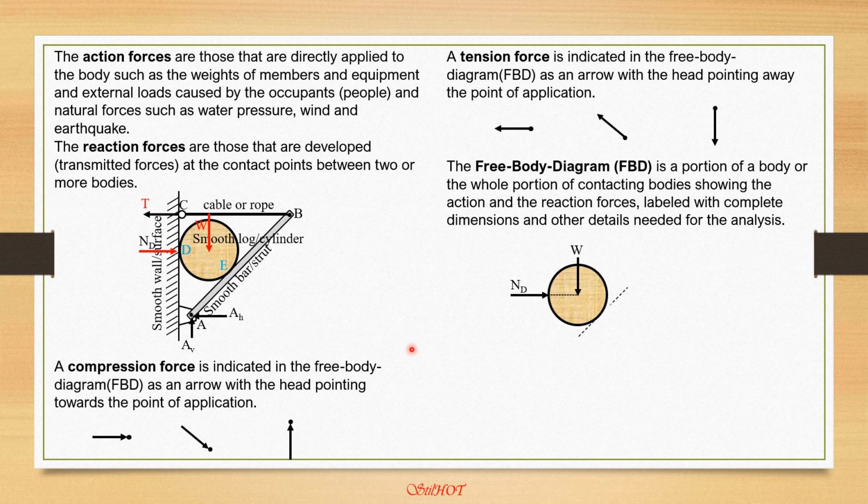At E, the reaction is also perpendicular to the axis of this smooth bar, and it is pointing towards the point of contact because it is a compressive force. Now, as I said, you have to treat this body as your body so that you can feel if the reaction at the contact point is tension or compression. So it is compression definitely, and it is directed towards the center of the cylinder or lug.